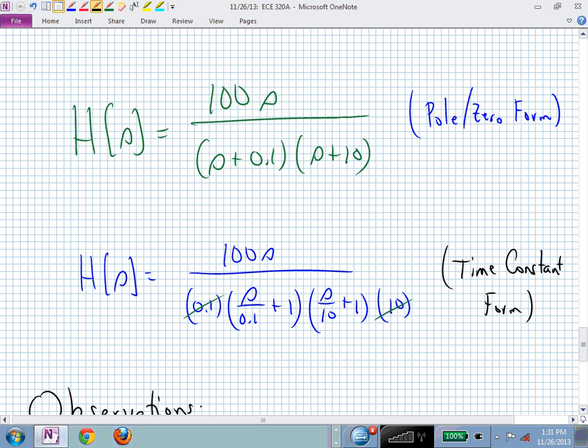Give it another pole. I feel like a cheerleader now. Give me a pole. At high frequencies, it's minus 90, right? Give me a 0. Plus 90. So they've canceled out, right? But then I give you a second pole, and now we have minus 90. What was I asking about, slope or phase? Phase? Slope, both. So what's the phase at high frequencies? I got all confused by cheering. Phase is minus 90, right, at high frequencies.